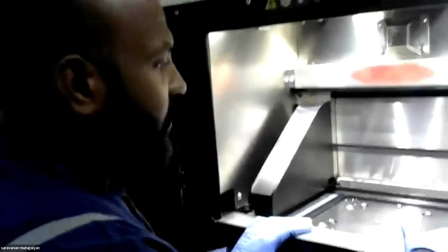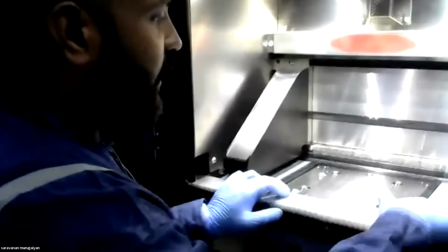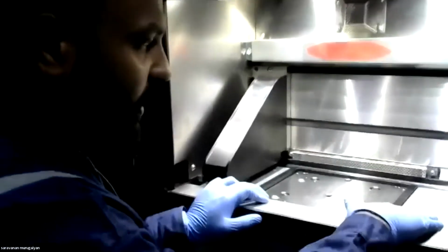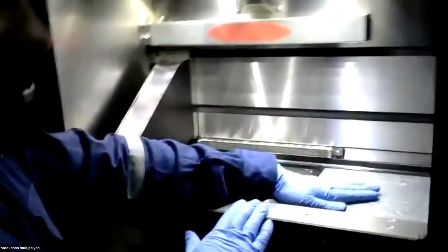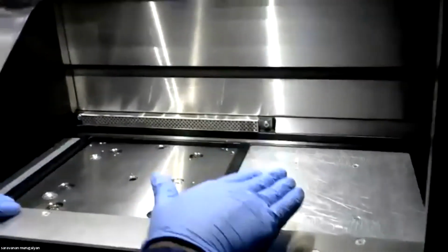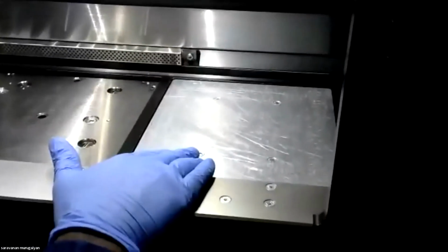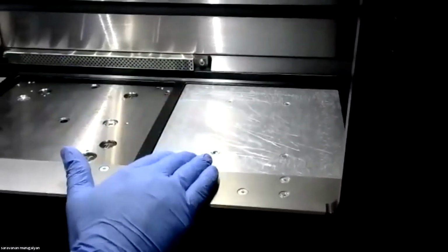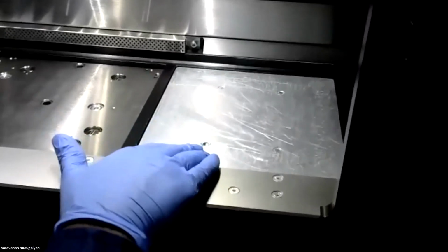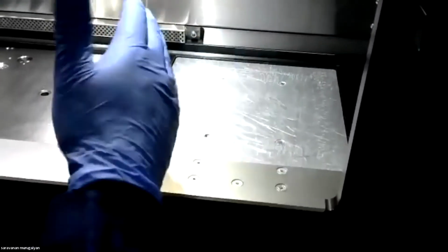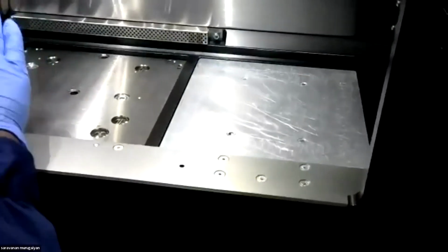And on the right that you see here is the dispenser duct. Currently, as you can see, the platform is at the topmost position. It can go down, and here we deposit the fresh metal powders. The main function of the dispensing duct, or this platform, is to feed metal powder to the recoating system.